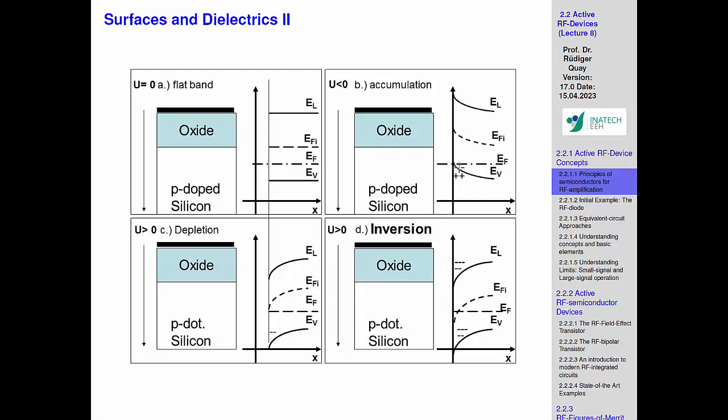The more interesting case, however, is that we are discussing the depletion, or the pushing away of carriers. What happens then is simply you take a positive voltage and you deplete this region under the oxide, which again is a very positive situation, because it means that you can really bend the bands down. Yeah?